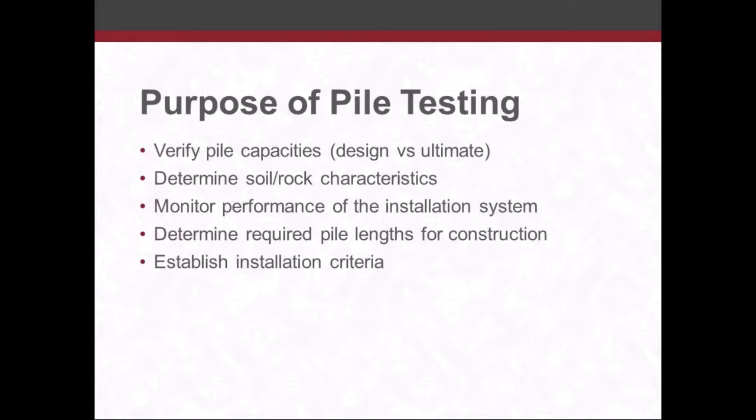We also want to establish installation criteria, which is going to be how many blows per inch or blows per foot is required to achieve a specific capacity, as well as the depth to achieve that capacity. And that brings us to question number 1.